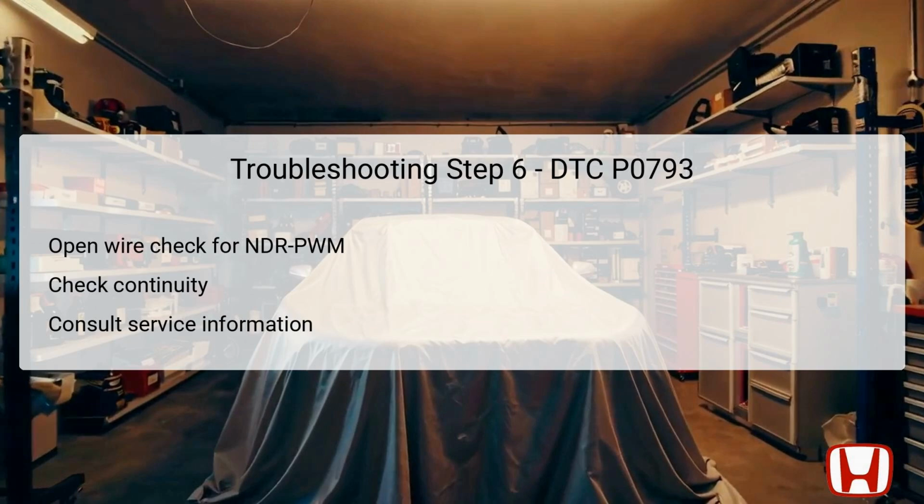If everything checks out with a functional wire, consult any authorized service information related to the DTCs for possible solutions or known issues in the system. If issues persist despite the wire's integrity, it may be necessary to replace the TCM if substituting a known good unit resolves the DTC. This systematic approach ensures you're addressing the root cause rather than symptoms, ultimately leading to a successful repair.